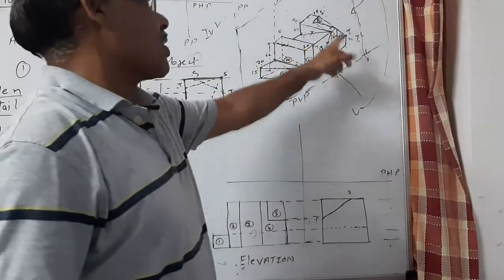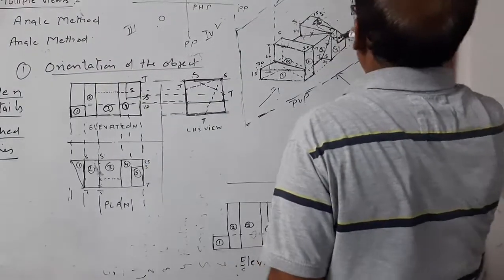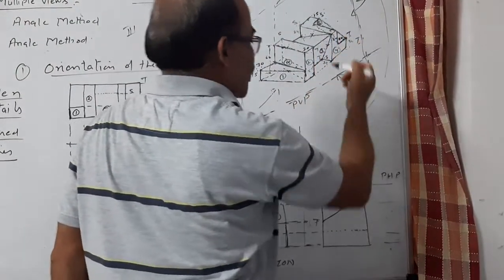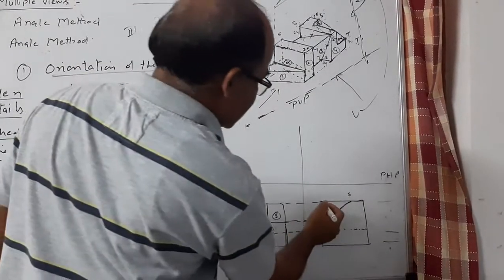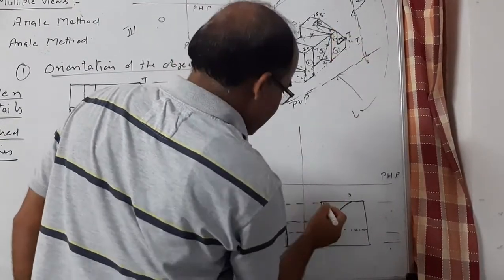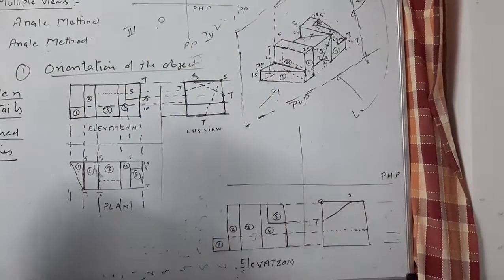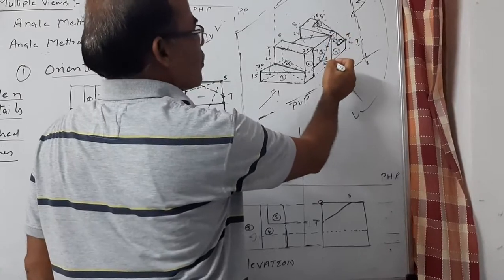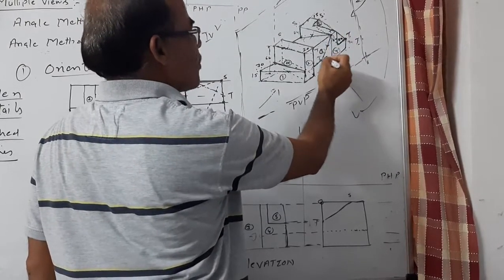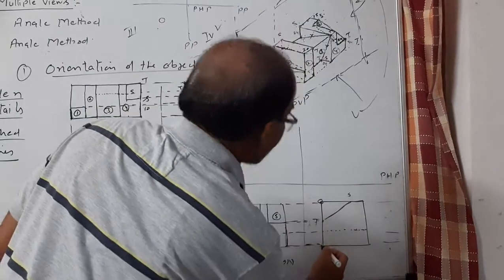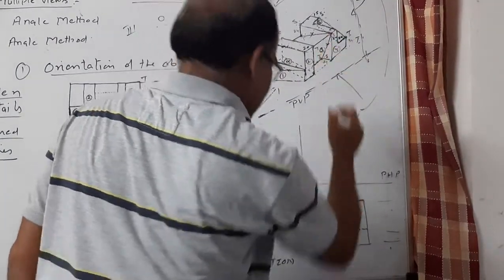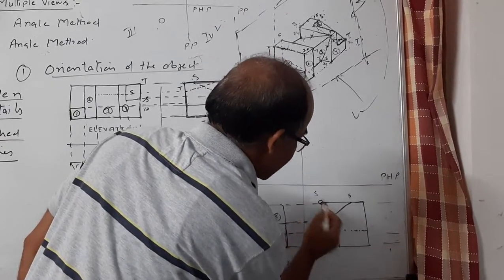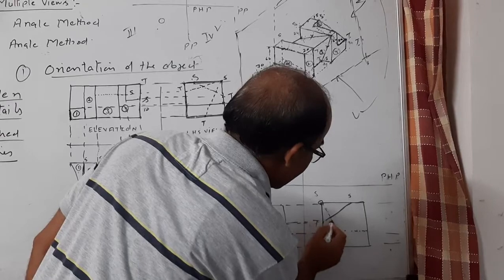Then these two dashed lines, since these are from this side, this corner where these two lines are starting would be towards the plane intersection line. So that is this corner. I have to start it from here. For this line, I have to move down by the whole height of this and then move inside 30. So this would be the starting point, this would be the terminating point, and the projection would be like this.